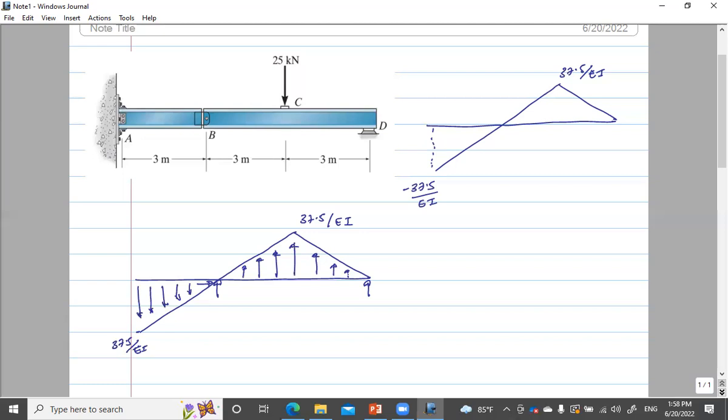Now in this beam, you just see this sort of loading. At any point you take, the shear force and bending moment for this load is equal to the slope and deflection in the real beam. So now we were interested in finding the deflection at C, right? This is A, B, C, D. We were finding the deflection at C.